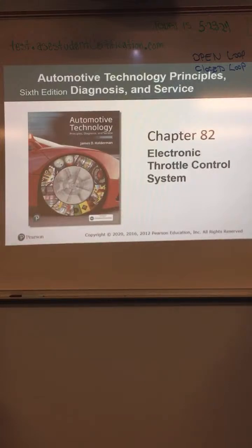The fuel pressure regulator is controlled by using an electronic pressure control valve. Pressure is 500 to 2900, we did already. Voltage 50 to 90 if it's GDI, 12 to 14 if it's port fuel injected. Stratified mode for 7. Decreased throttle response for 8. Less need for fuel on acceleration is B for 9, we did that one too. And we did 10.